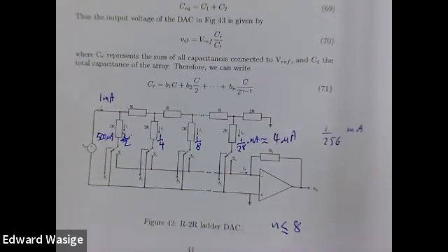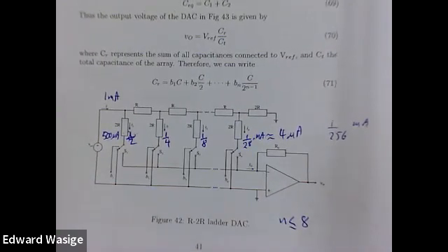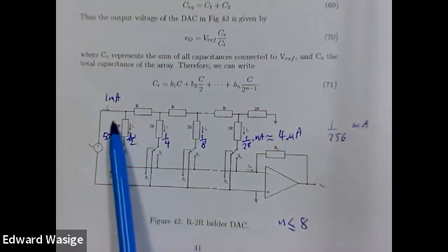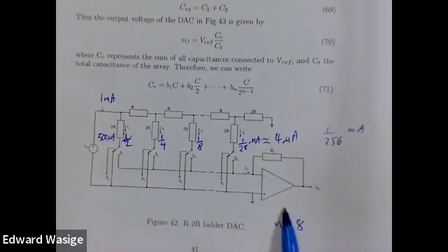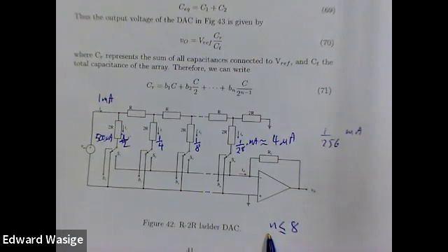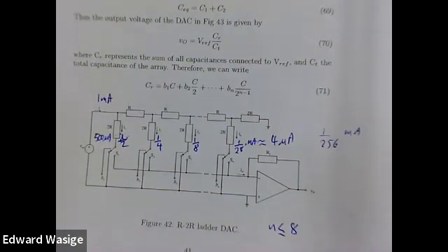So for all the Nyquist rate circuits, N is less than 8 because for the highest bit, the contribution, either the current for the resistor base types or the voltage for the capacitor base type, is quite small compared to the largest contribution. To still do that accurately with N equal to 8 or less, we can design that and it works. Beyond that, we start to struggle. So that's why it's limited to 8.